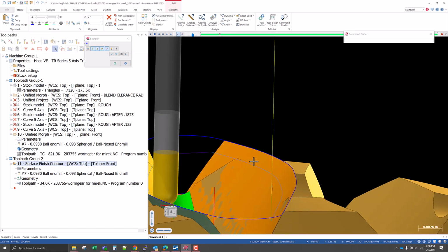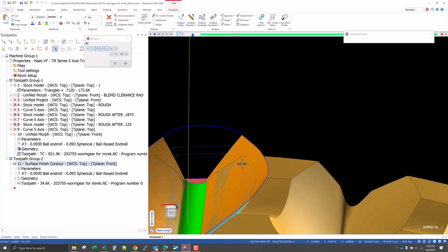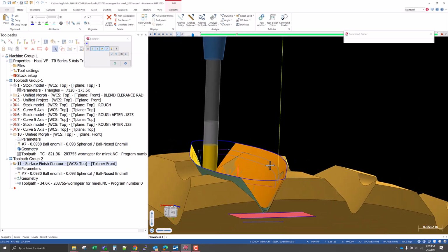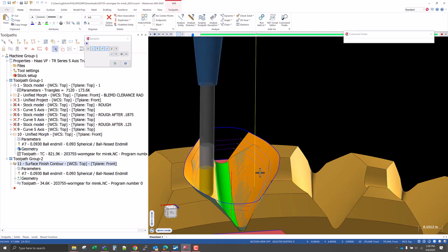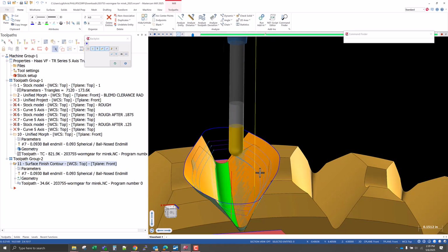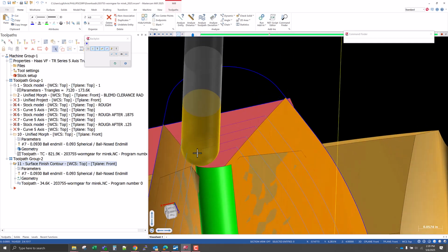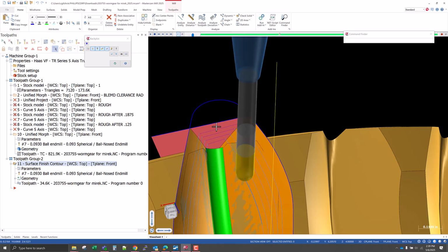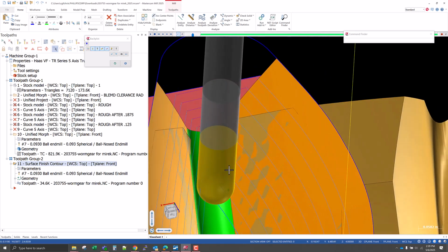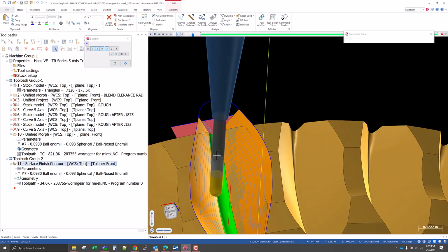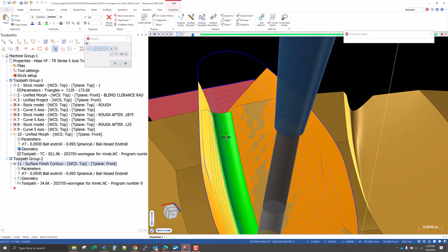And so with some of the other toolpaths, we could use stock as a way to tell it exactly where to cut. We can't really do that with this one. And we still do have this kind of sharp transition line. It's not the end of the world. It looks better once we get down into that fillet radius here. I mean, that's pretty nice motion.